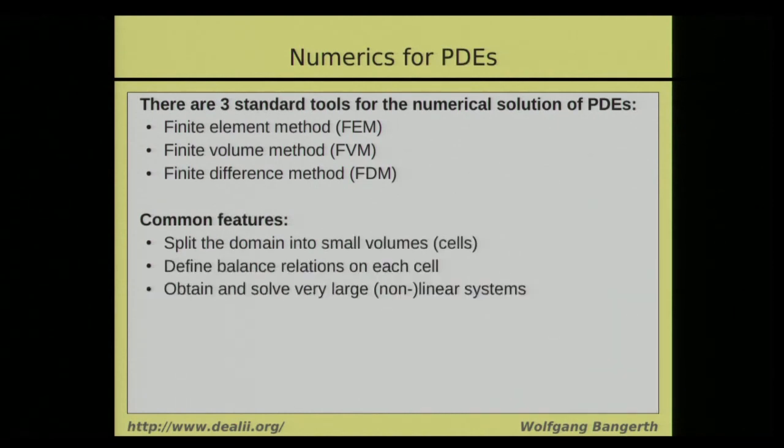Then, by and large, the way you can see a discretized partial differential equation on a mesh is that you have to define balance relations. Essentially, if you think of flow problems, for example, the balance relationship would be whatever flows out of a cell must flow in on another side. So most of the PDEs that we write essentially come from these sort of balance relationships. And then when you have these balance relationships between cells, you obtain a typically very large linear or nonlinear system that you have to store and solve.